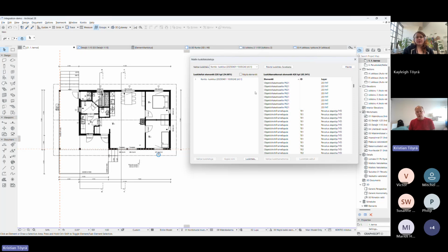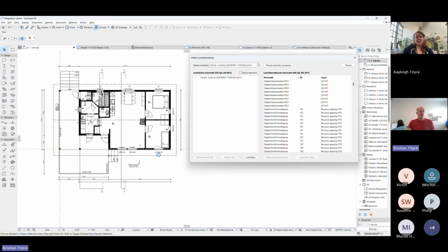So we are using layers classification, the parameters of objects, the parameters of walls, the sizes, everything, to find out that this is the wall or this is the bit of roof or slab we need. But anyway, we still have the classification system, and it's based on many recognition of elements. And you can see, I'm sorry, this is all in Finnish. This is for Contio's internal use, but 226 elements are classified here, and 426 are unclassified. So about 1/3 of the elements are classified.